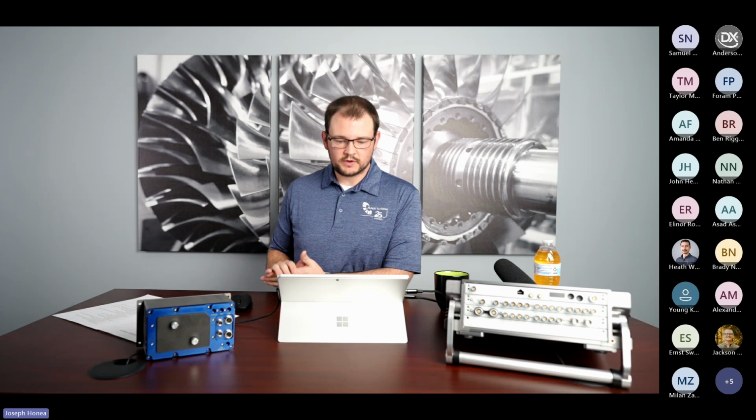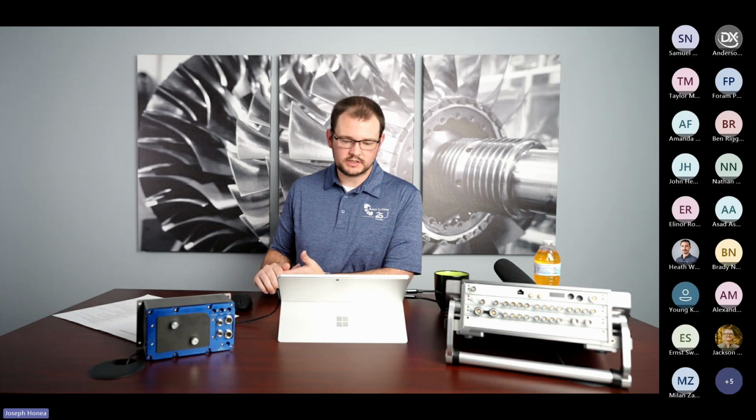So for devices that do not support any time stamping, an input channel of the device can be utilized with an iRig input, and then using the iRig signal for that device, the time stamping for the data coming through will be based off of iRig time at that point.